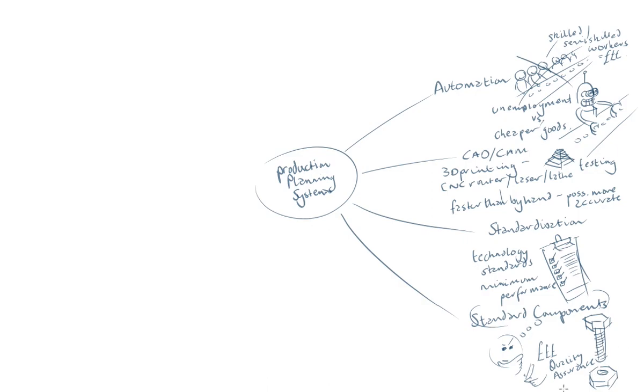Just-in-time manufacture concerns the purchase of standard components and the manufacture of parts to arrive just in time, i.e. they don't want lots of components lying around just waiting to be used. It's much more efficient to have these components arrive just in time, ready for manufacture. The alternative to this is to actually store these components in vast warehouses, which costs money. There's security to think about. Sometimes the warehouses themselves need to be climate controlled, so it can be really expensive.